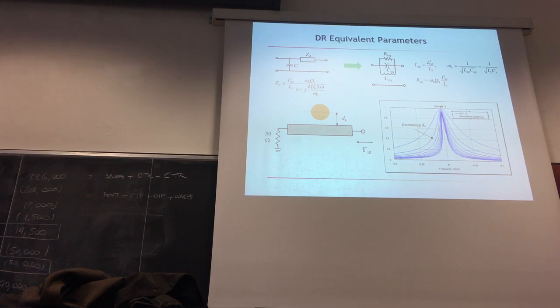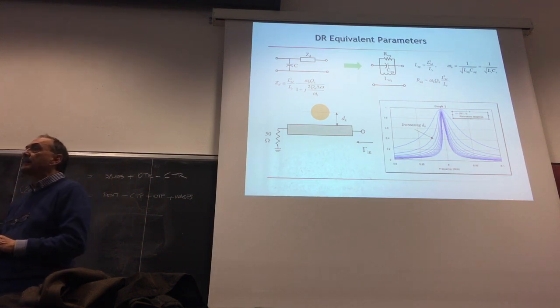Because we have seen that the stability of an oscillator is quite related to the rate of variation of some particular parameters associated with an element determining the oscillating frequency. When this happens, we have the possibility to constrain the oscillating frequency just around where this very fast change of the element parameters happens.